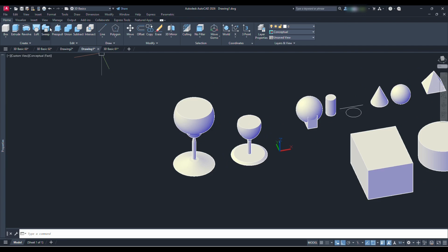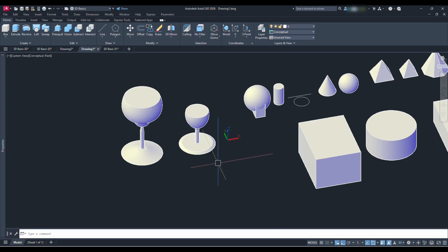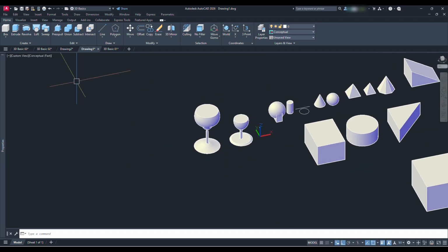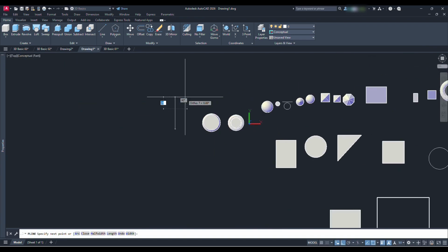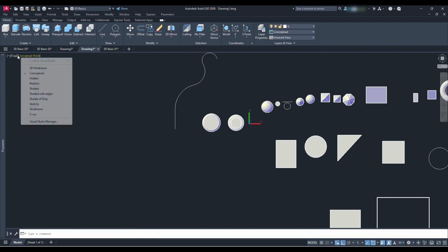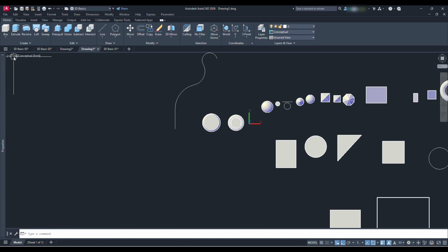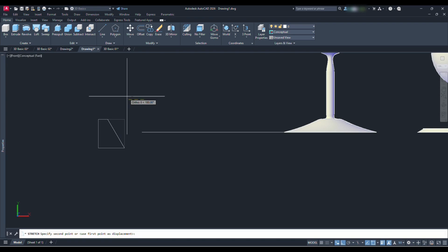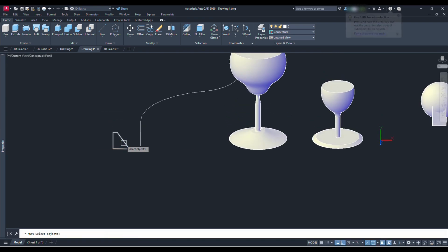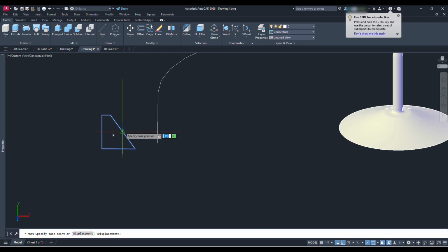Now sweep. This command is similar to extrude, but it extrudes a closed shape along the desired alignment with bends and curves. Let's see how it works. Let's draw a polyline for the route of our extruding section on plan view. Change to front view and let's draw a required closed polyline. Let's move this section to this end of the alignment. We can select any corner as necessary.